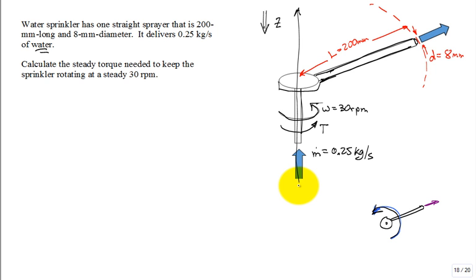So we introduce a control volume, and then we apply our balance or conservation statement of angular momentum to that control volume. Now, that control volume can move and rotate with time. Just like we could have a constant linear motion with our control volume, you can have a constant rotational motion with our control volume. That's what we're going to do. So our control volume is going to be something like this. It'll cut right here because I like fluid cutting across the boundary of our control volume. It'll come up through the air, out through the air. It'll cut right there through the fluid stream that exits that control volume. Air, air, air, close it. And I know that I'm showing a 2D control volume, but think about it as 3D.